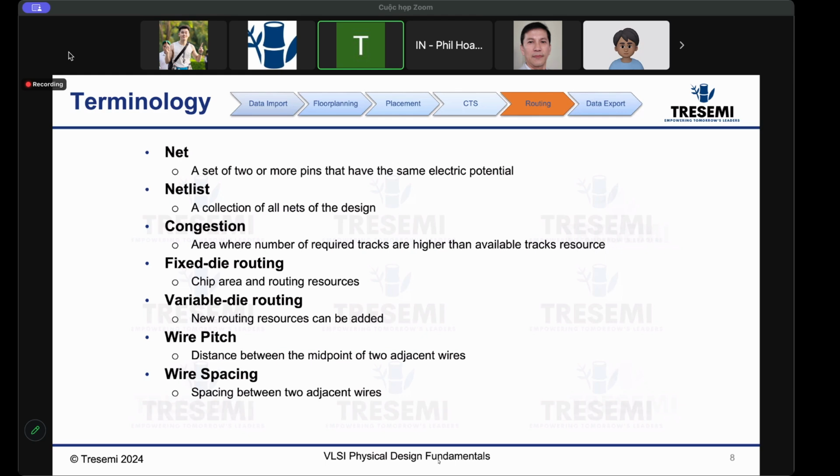Because ultimately, if you have more wire than the routing resource, then you're not going to be able to route the chip. It's as simple as that. Not overall, but locally, if there's an area of the chip that you simply can't force more wire into, an area that has no routing resource, it's not going to work.